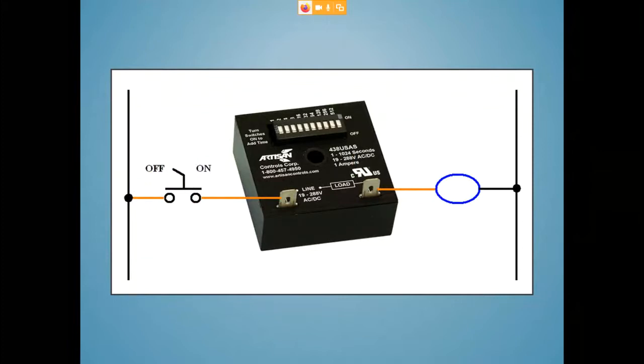So if we look at ladder logic, you could see here we would have an enabling switch to enable the timer, and then based on what these seconds are, you would wire this into your relay to start a motor or whatever it is that you want to turn on. So this would be how we would wire this thing up into some ladder logic.